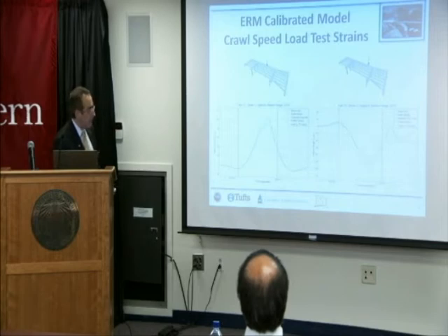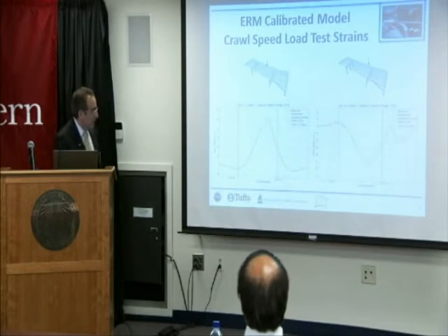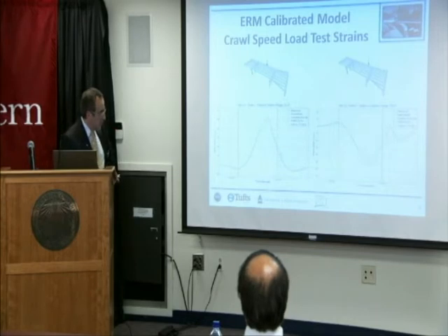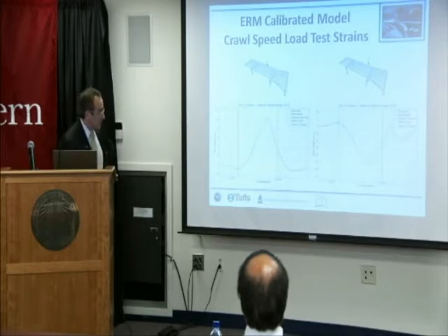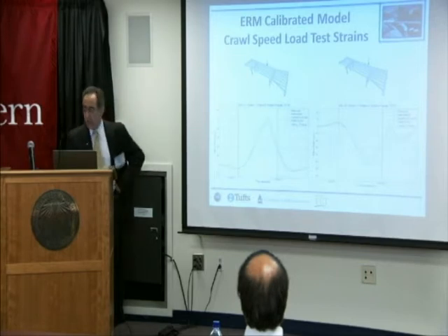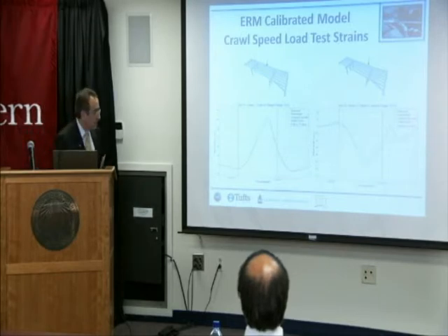North pier and north abutment. So this is when the triaxle truck, a 72 cube truck, goes over the bridge. With the initial model, we had some distance to the measured data out here, and there were several layers of global model updating, including updating concrete properties so that we got closer, and then adding safety curves that were made out of concrete, and they added significant stiffness, and we got closer.